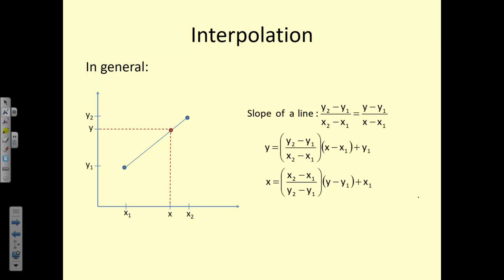Okay, so interpolation is used to calculate the enthalpy or calculate the quality. It's also used sometimes to find property values that are in between values on the table. Hopefully this is familiar to you. It's just using the equation for the slope of a line. So if we have two different points on this line, we can say that the slope of those two points is equal to one another in that line that's connected. And then to find this third point, we say, okay, I know it's somewhere along that line. Let me figure out where it is. And that's the basis for interpolation, or what we use interpolation to do in this class.